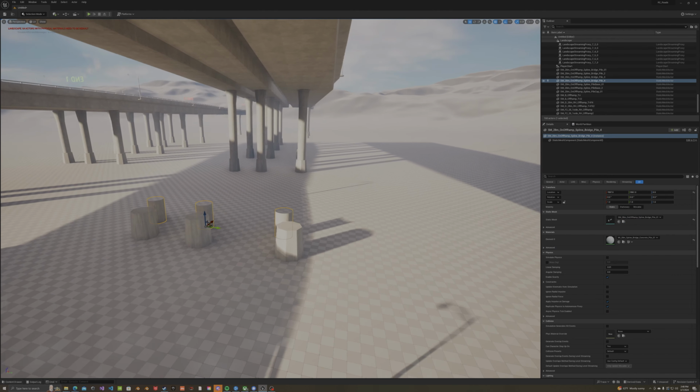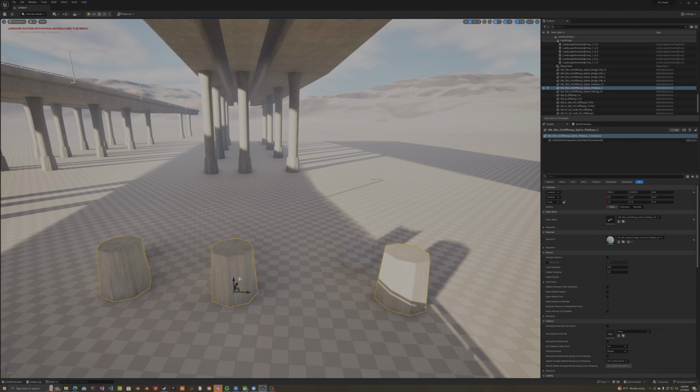Now I want to get exactly on where these are. So what I'll do is come over here to location. With these base pieces selected, I'll go to location, right click, copy. Select my mid section. Go to location, right click, paste. Alright, now we're exactly where they are.